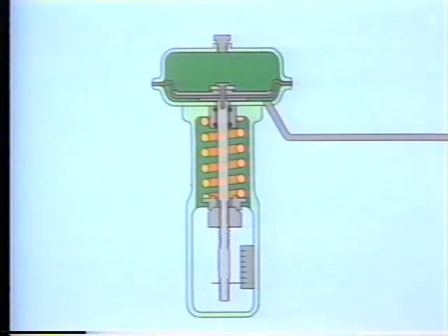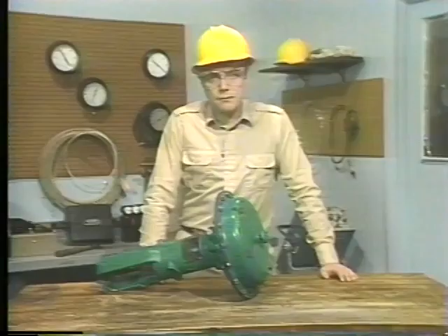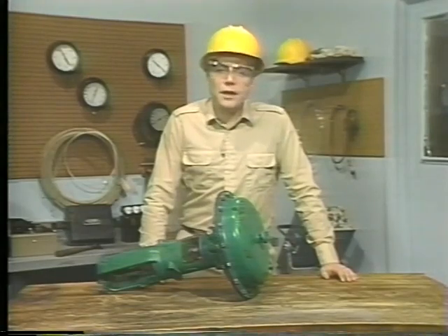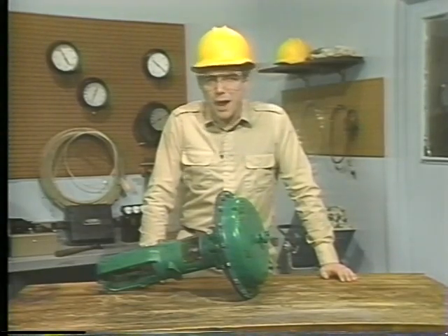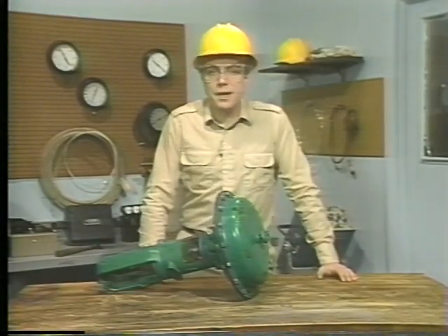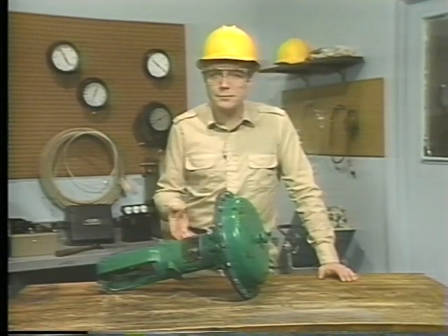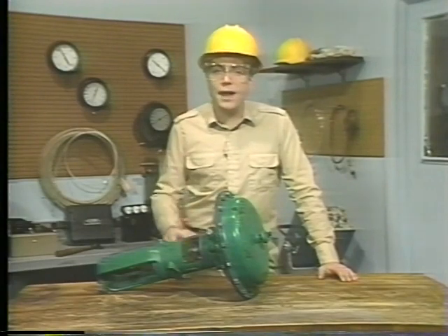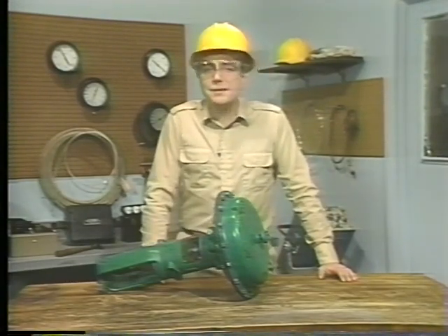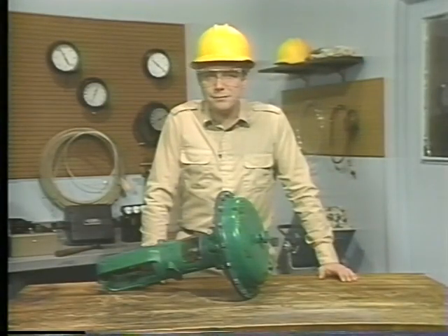This actuator is classified as a single-acting diaphragm actuator because it has only one port for control air to enter, and control air pressure acts on only one side of this diaphragm. So essentially, all of the internal parts of the pneumatic diaphragm actuator serve one purpose: to move the stem of the actuator in response to changes in air pressure. This provides one way that we can operate control devices, such as valves or dampers.